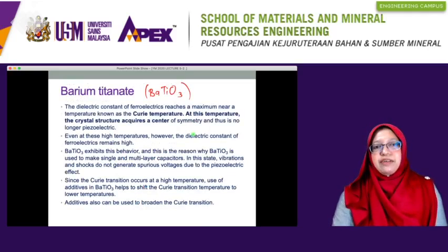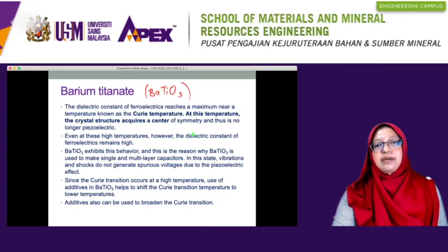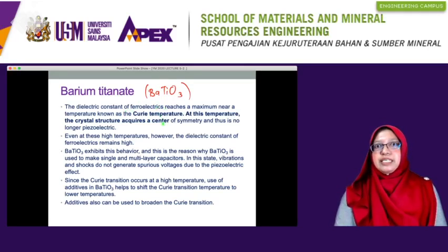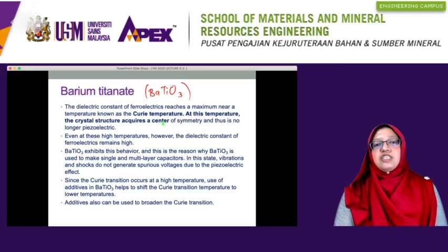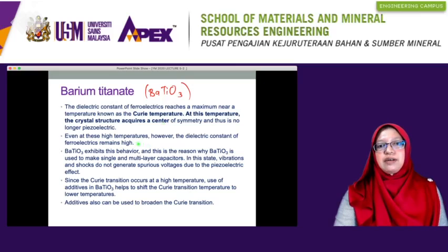Next, we have barium titanate, with the chemical composition BaTiO3. The dielectric constant of a ferroelectric reaches a maximum near a temperature known as the Curie temperature. At this temperature, the crystal structure acquires a center of symmetry, and thus it is no longer piezoelectric. Even at this high temperature, however, the dielectric constant of ferroelectrics remains high.